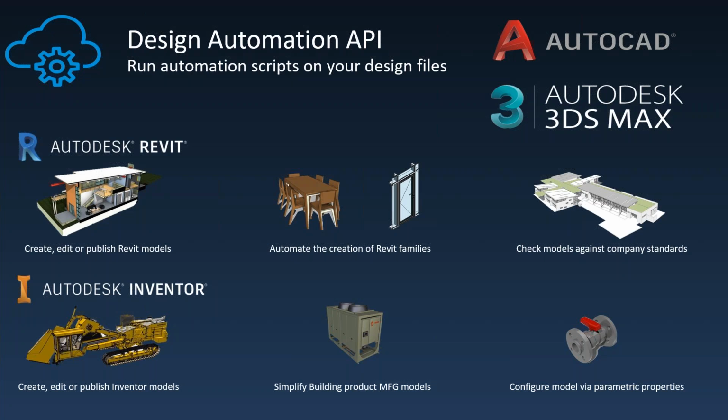So imagine that I was to have a Revit file that gets into BIM 360 in a specific folder with just a model, you know, just one basic 3D view with everything inside, no sheets, no 2D views, no nothing. Well, there will be 2D views, obviously, for the design itself, but not really any specified sheets. So what we can do is use webhooks to understand, oh, there's a new version here. So that new version kicks in and opens Revit in the cloud, and according to a set of rules, is going to generate the sheets automatically. And that's going to be my new version in BIM 360 Docs.